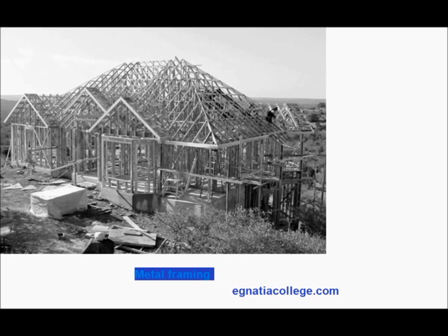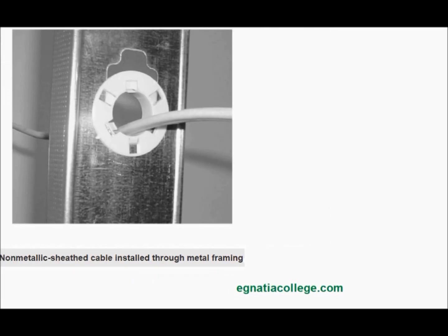The gauge must be taken into consideration before using certain tools, stud punch, actuated tools, etc., and special mounting devices, box hangers, conduit brackets, etc. Where electrical non-metallic sheathed cable is installed through metal framing, a bushing or grommet must be installed prior to installing the cable.